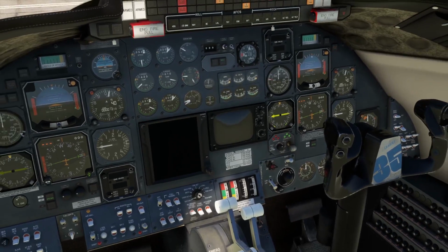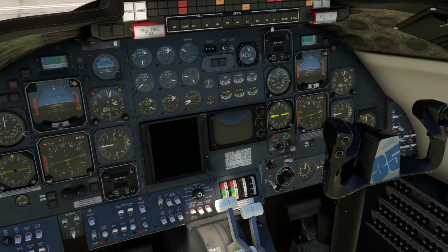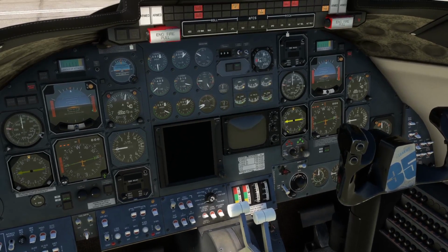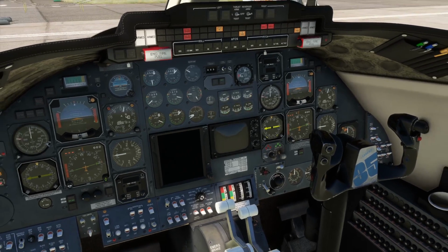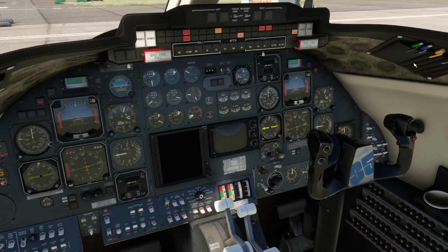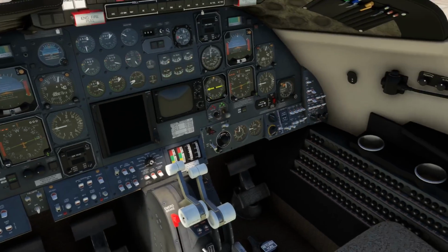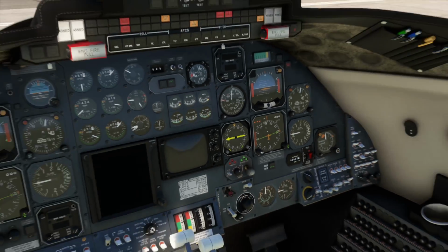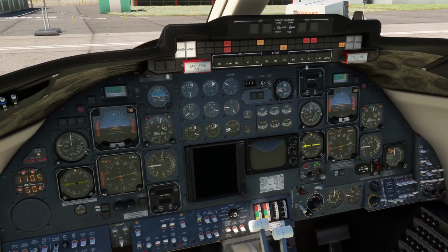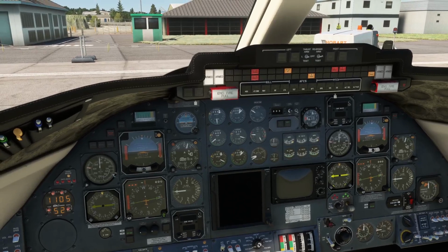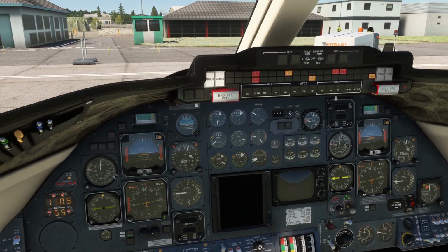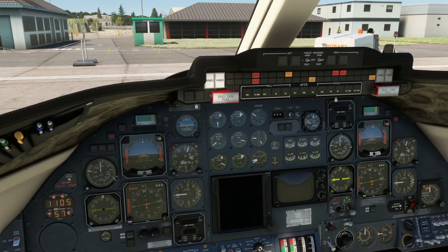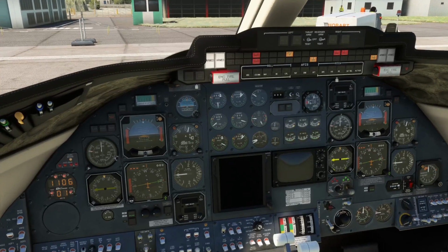And finally, the only 2 systems that you can't operate just from the battery are the air conditioning unit and the auxiliary heating unit if it's installed in this aircraft. The air conditioning unit is controlled over here. Basically, those 2 systems have such a heavy amperage draw that there's a protection that means you can't turn them on unless you've got a generator running or GPU connected. They won't operate off the battery.